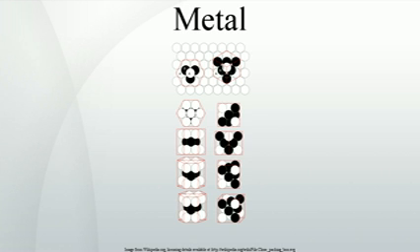The movement or displacement of such mobile defects is thermally activated, and thus limited by the rate of atomic diffusion. Viscous flow near grain boundaries, for example, can give rise to internal slip, creep and fatigue in metals. It can also contribute to significant changes in the microstructure like grain growth and localized densification due to the elimination of intergranular porosity. Screw dislocations may slip in the direction of any lattice plane containing the dislocation, while the principal driving force for dislocation climb is the movement or diffusion of vacancies through a crystal lattice.